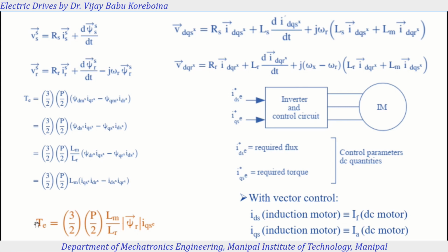Now what will happen in torque control also, when you go to the inner loop torque control, you will get the reference torque, but where do you get the actual torque? The actual torque has to be either sensed, which is impractical, keeping torque sensors. So now it can be estimated. You can estimate it from this equation by flux and IQS, the mathematical equations. You can estimate the actual torque. So when you have the actual torque and a reference torque, then you can process. Likewise, by controlling IQS, you can control whatever torque you require.